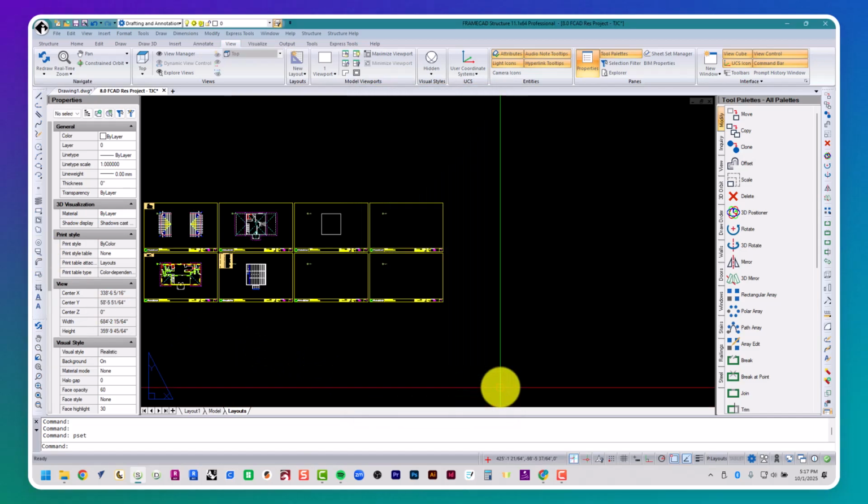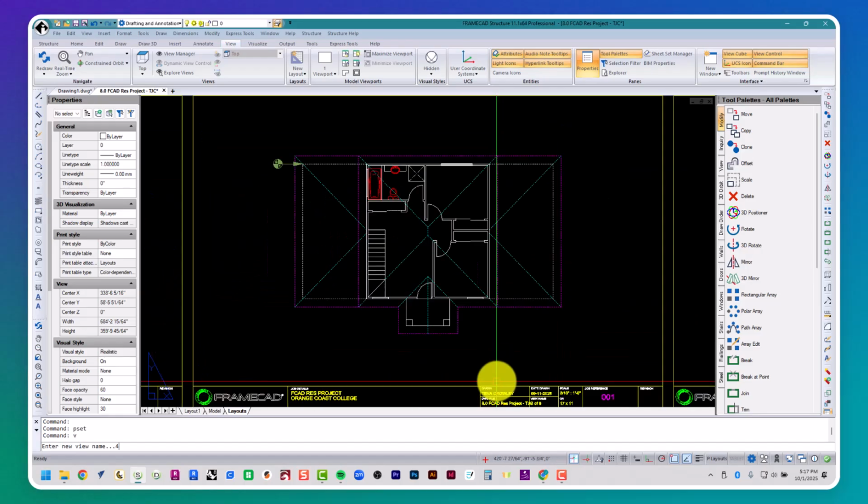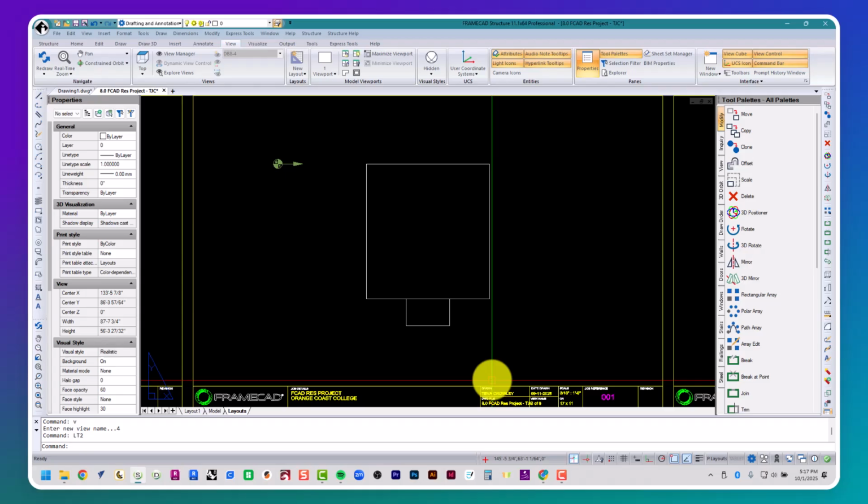Let's quick navigate to border number 4. Ensure that your second floor block is not visible on its temporary layer by using the LT2 command to turn it off. You should see a white polyline which represents the footprint of the second story walls as well as the deck connected to it. We're going to initiate the add framing item command by typing in add.